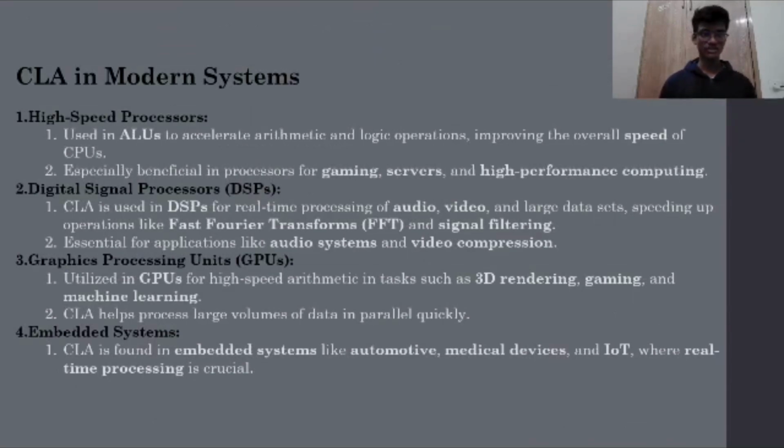CLA in modern systems. High speed processors use it in ALUs to accelerate arithmetic and logic operations, improving the overall speed of a CPU, especially beneficial in processors for gaming, servers, and high performance computing. Digital signal processors, DSP. CLA is used in DSP for real time processing of audio and video and large scale data sets, speeding up operations like fast Fourier transforms and signal filtering, essential for applications like audio systems and video